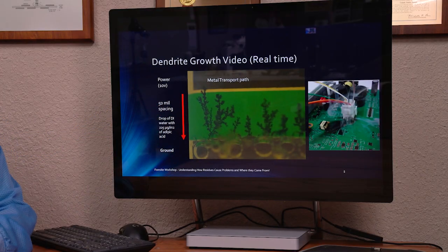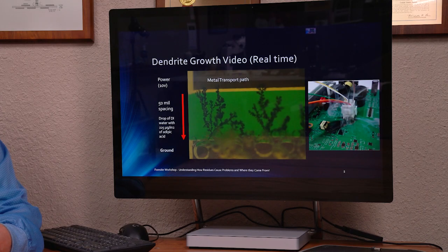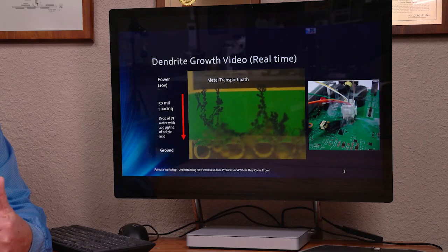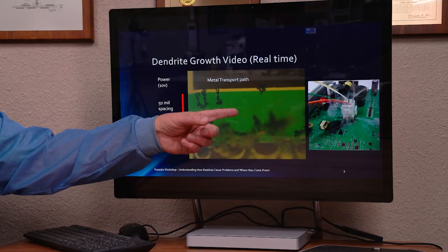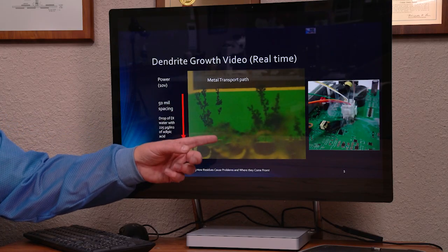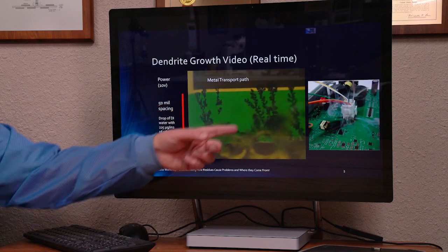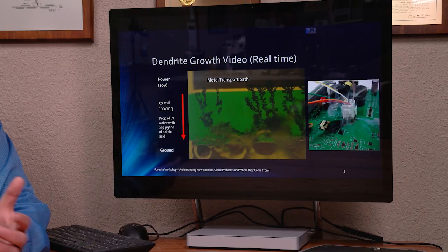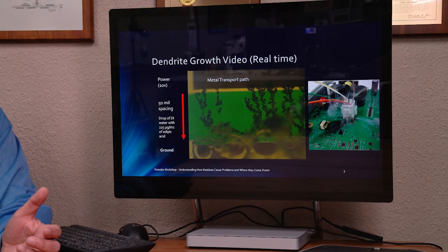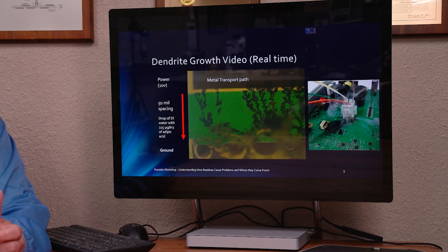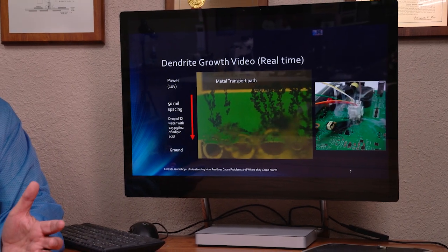Now you see that it will actually short, but since we're only at 10 volts and we're at 0.25 amps of current, we're not able to carry that. So what we see is it blow open, and we see that those remnants really don't connect anymore. And then since the solution is still full of weak organic acid, it's got 225 micrograms per square inch of adipic acid, it's continuing to feed that mechanism. That mechanism will continue to grow and short as long as there's a fluid bridging path.